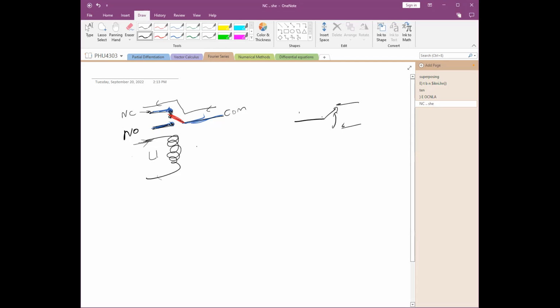So what is the advantage of using a relay? Now, obviously, a relay can be used to control a larger current from a smaller current. For example, there are different voltage relays. You have 3 volt, 6 volt, 12 volts, 24 volts, and 230 volt like that. Usually, this voltage is the voltage applied to the coil, the electromagnet.